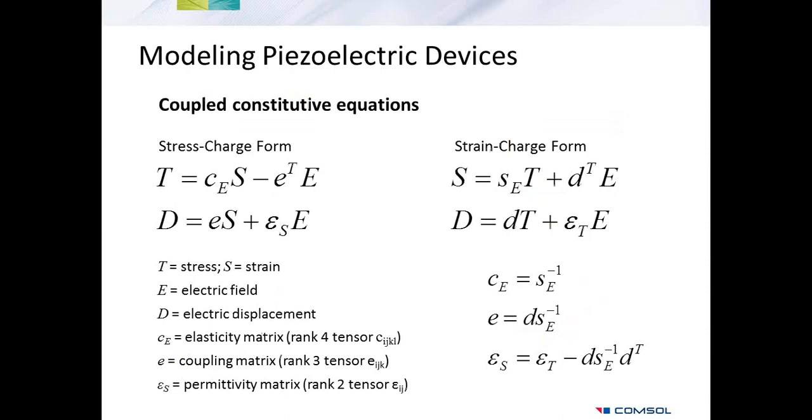Since modeling the piezoelectric effect involves accounting for both structural and electrical effects, the simulation is inherently multiphysics in nature. COMSOL has built-in tools and interfaces for modeling piezoelectric devices. This interface provides a predefined multiphysics coupling between electrical and structural equations. The electromechanical coupling in piezoelectric materials is modeled using a set of coupled constitutive equations, as shown on this slide.